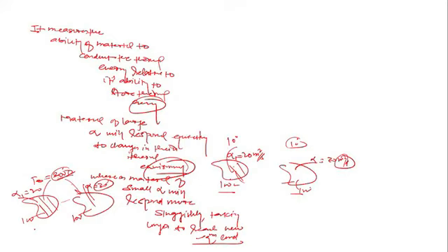This is alpha equals K by rho Cp, the thermal diffusivity. Clear, beta? One more thing, thermal diffusivity is a controlling transport property for transient conduction problems. Transient means unsteady state, because time comes into the picture. That's why you should write this very important point: thermal diffusivity is the property of a material, or transport property, for transient conduction, where time comes into the picture, unsteady state conduction.